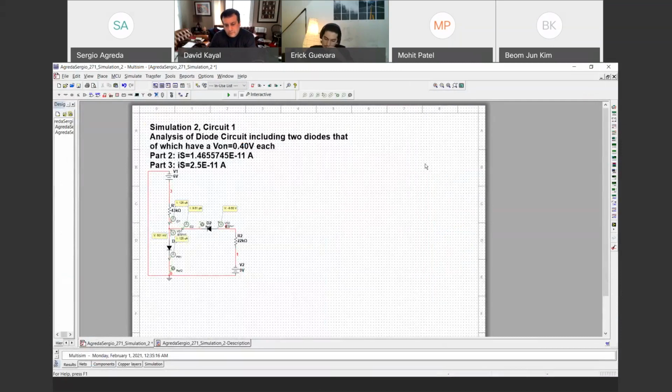I just had a question. Yes. So when the diode is off, it's always going to have a current of 0, and the voltage will always be negative. Depending on where it is, yes, there's no current running through it because it behaves like an open circuit. You basically cut a wire, and no current is able to run through it. In this case, it's a diode that doesn't permit the current to run.